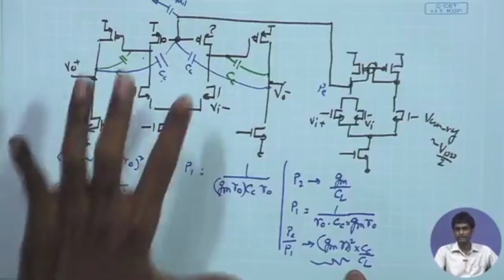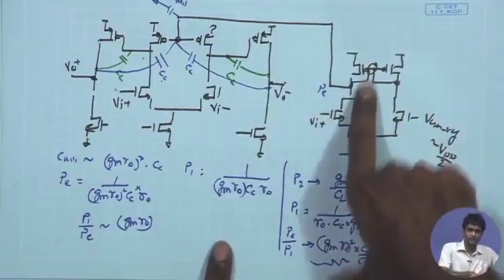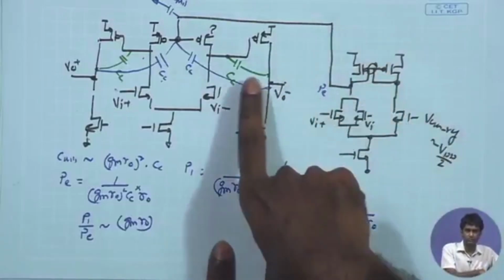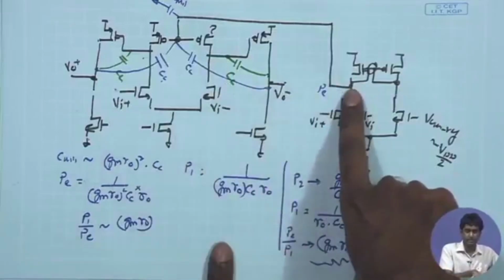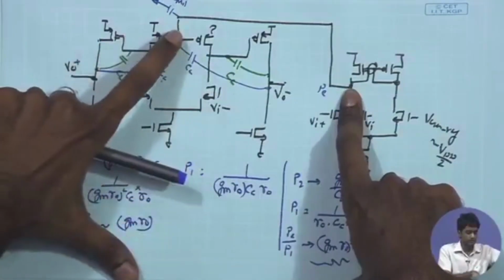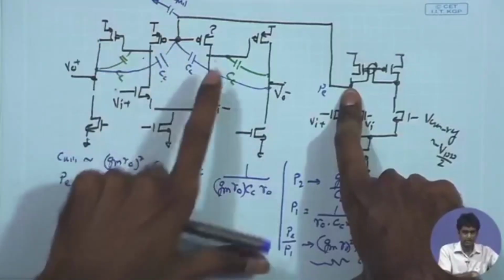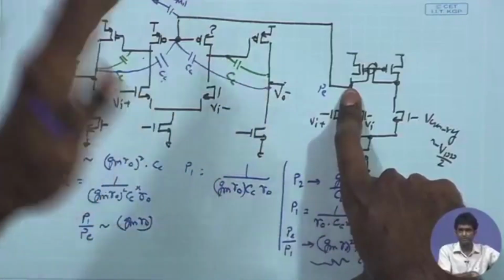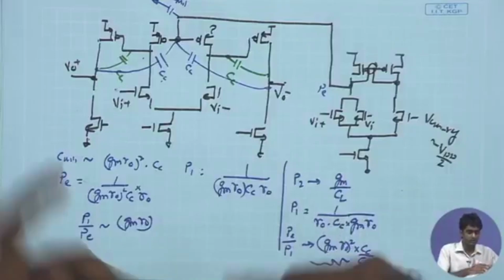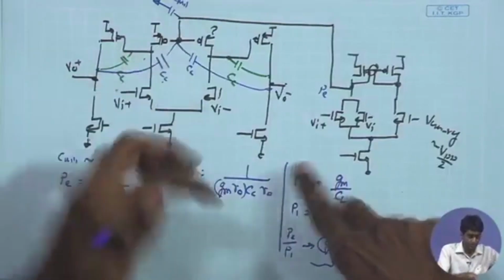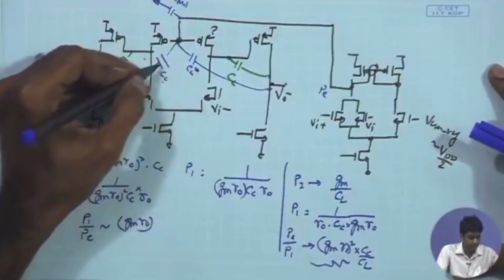And in that case, you can also possibly go for an Ro over here which is much larger than the Ro of the first stage of the differential amplifier. In that way, possibly you can still try to achieve a C Miller over here which is much larger than the Miller multiplication of Cc for the differential operation. So there are two constraints that will come into picture: you need to use a large, let me call this Cc1 just to distinguish, or Cc star.